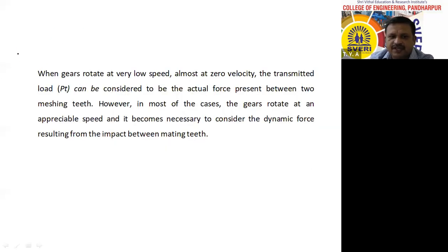Therefore, when gears rotate at very low speed, almost at zero velocity, the transmitted load, that is PT, can be considered to be the actual force present between two meshing teeth.